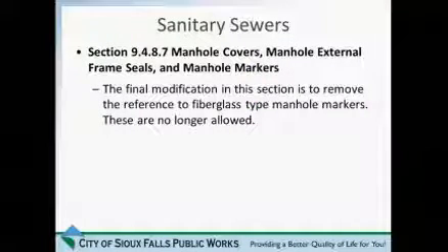Another piece in this section is removing the reference to fiberglass type manhole markers in our drainage areas. Wherever they're outside of street areas, we try to mark them for easy access and for maintenance. We no longer ask for fiberglass type manhole markers. We use PVC style manhole markers in these areas. So it's a cleanup piece to remove that reference to fiberglass.